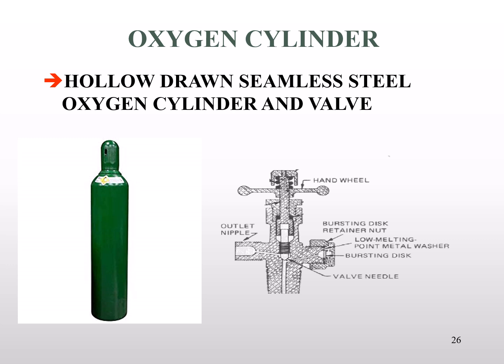Oxygen is green. It's in a cylinder that's made of seamless steel. It'll have a brass valve installed in it. And in that valve, there's a disc that's always open to the bottle to allow pressure to discharge in case that disc melts or the pressure overcomes the disc's structure. That allows the bottles to dump excess pressure, keeping the bottle safe and keeping it whole.